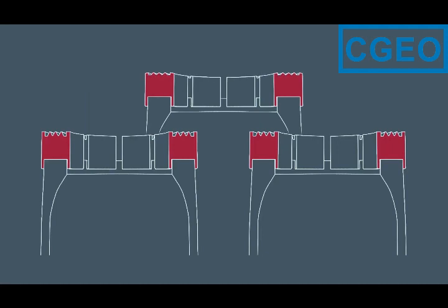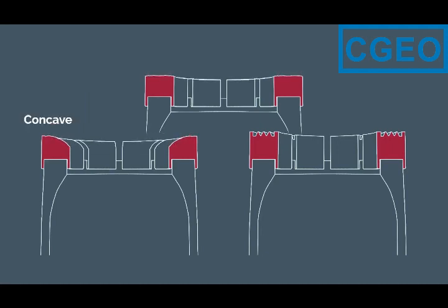Examination of a used bit can provide the driller with useful information. If the driller is using incorrect drilling or flushing parameters, this can be seen from specific wear patterns on the bit face. For example, too low RPM may result in a concave bit.